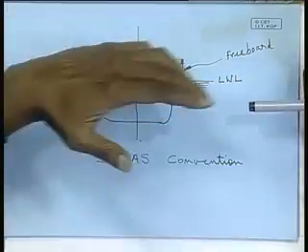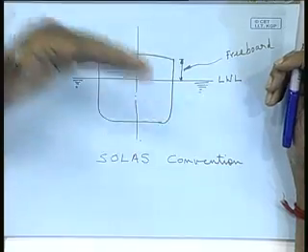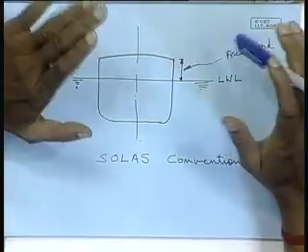have less than that. When may it become less? Suppose I have loaded, I overload it. So, overloading is not only a problem from the structural point of view, but it is a problem from the safety point of view. So, that is not permitted. Anyway, what happens in case of higher density cargo, right? You load to a certain extent, the way you design, and your vessel very easily attains the load water line, I mean it sinks to the required draft.